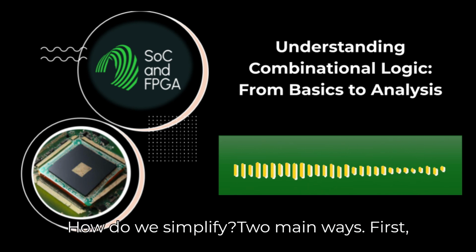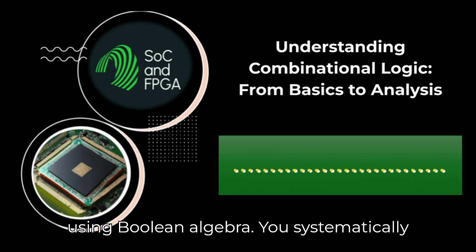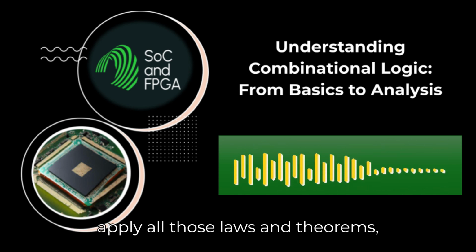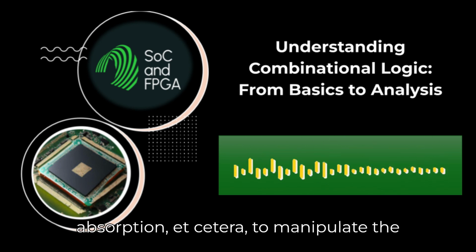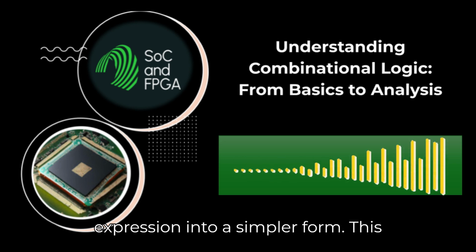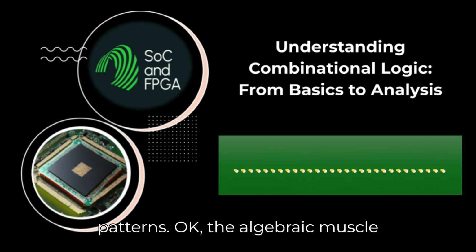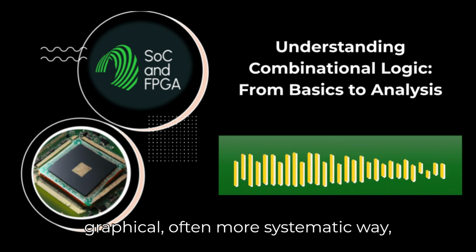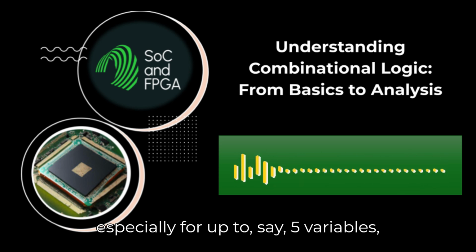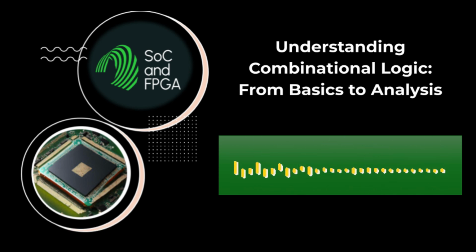How do we simplify? Two main ways. First, using Boolean algebra. You systematically apply all those laws and theorems, identity, distributive, De Morgan's, absorption, etc., to manipulate the expression into a simpler form. This takes practice and recognizing the patterns. Okay, the algebraic muscle approach. What's the other way? The more graphical, often more systematic way, especially for up to, say, 5 variables, is using Karnaugh maps, or K-maps. Ah, yes, K-maps.